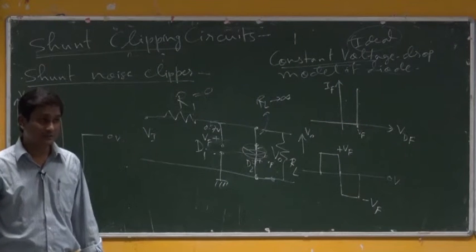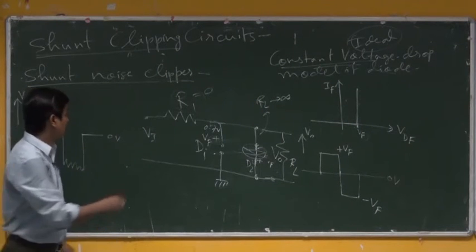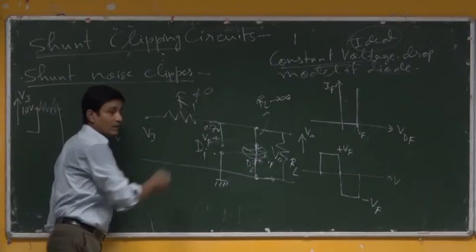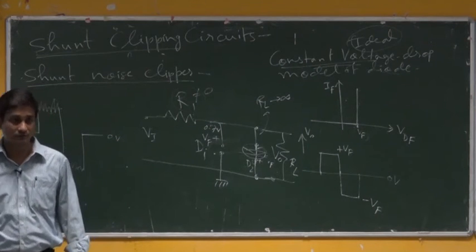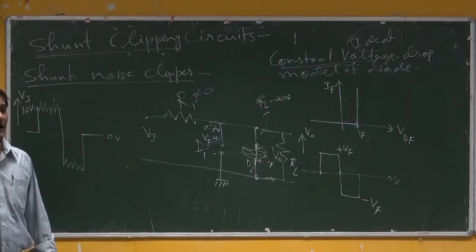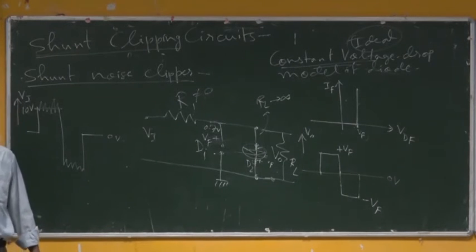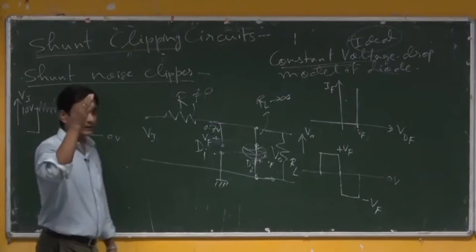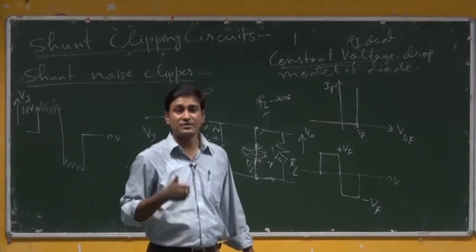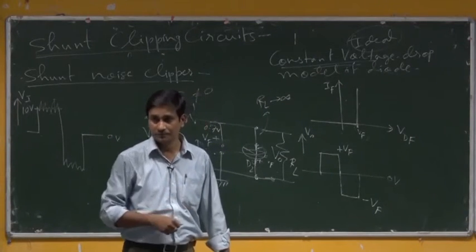That is why the circuitry we are considering here always involves an R1 non-zero value, so that we will have a maximum limit of current flow even though the diode is short circuited, or the voltage across the diode tends to 0.